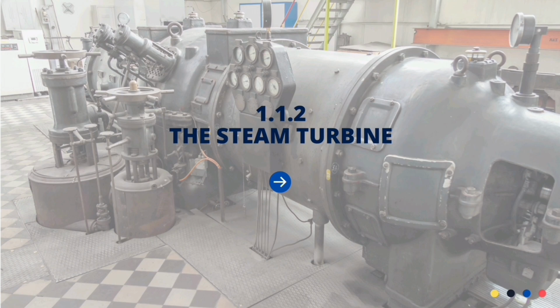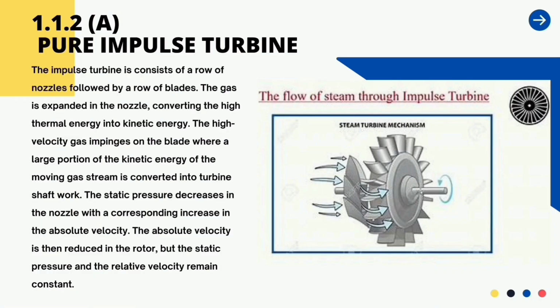The steam turbine. Pure impulse turbine. The impulse turbine consists of a row of nozzles followed by a row of blades. The gas is expanded in the nozzle, converting the high thermal energy into kinetic energy. The high velocity gas impinges on the blade, where a large portion of the kinetic energy of the moving gas stream is converted into turbine shaft work.